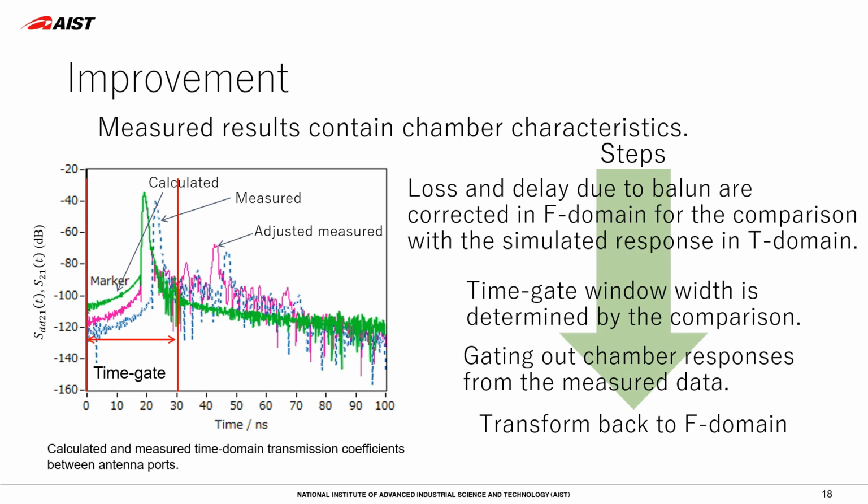Similar response can be found when the unexpected multiple reflection in the system happened. We investigated the measured data in 2 dimensions, in frequency and separation, carefully, and found that the wavy response was caused by the residual chamber reflections. We simulated the site attenuation between 2 antenna ports and used it for improvement of the measured data.